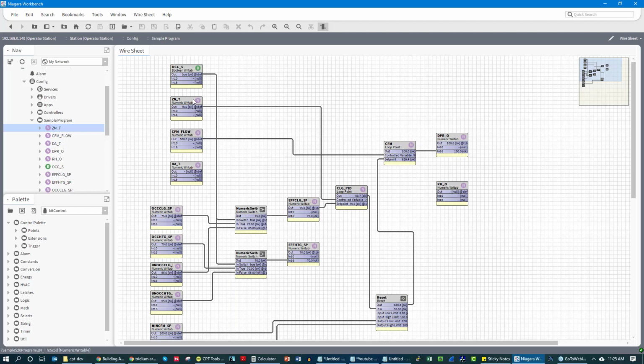So if you wanted to troubleshoot why a zone or a space was cold, you could look at the histories to see where was the damper position, where was the zone temp, and where was the discharge air temp at this point in time. And that's the benefit of histories and trends. And we'll talk through why the 15-minute interval is used and how that came about and the difference between interval and COV in just a second.